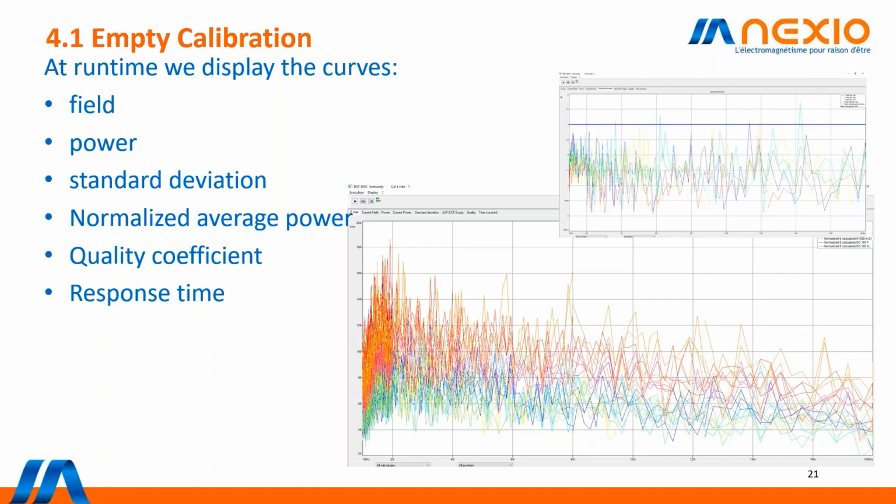When you use the continuous rotation, the D160 allows only the calibration on EUT. In this case, because we need to have the maximum on one complete rotation, we would recommend to put the spectrum analyzer on span 0 and max hold. And in this case, at the end, we'll measure directly the maximum. So it's the best way to measure the maximum on one complete continuous rotation.